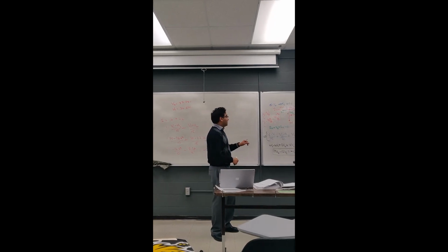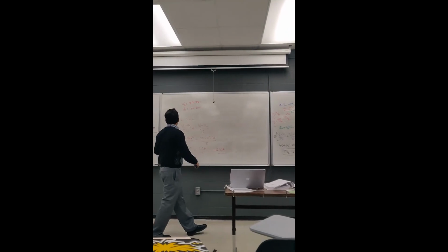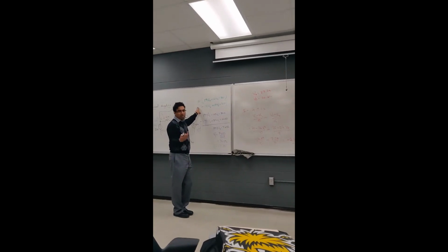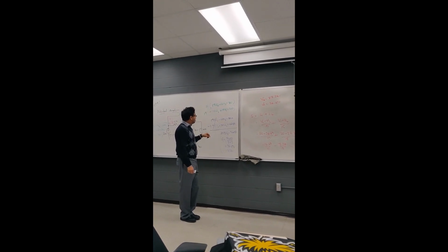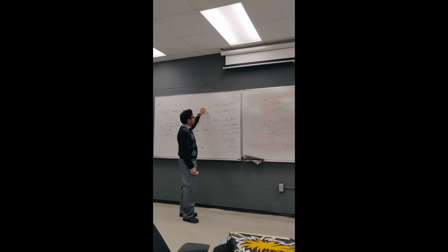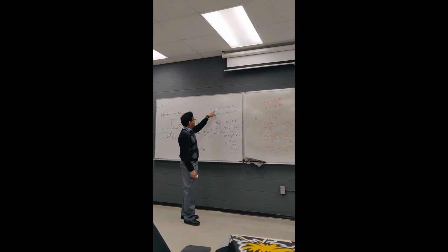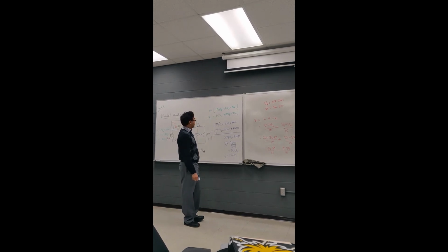So we have 2 unknowns, 2 equations, and I solve them here. There are many methods: substitution method or cancellation method. Here, I multiplied equation 1 with 10, which is the coefficient of V2 in the second equation, and the second equation with 19, which is the coefficient of V2 in the first equation.